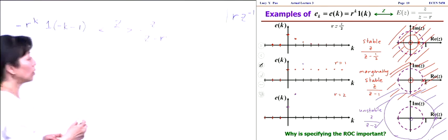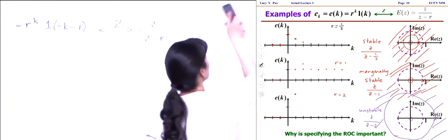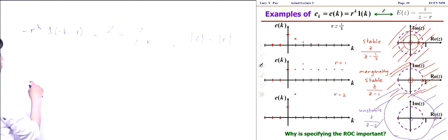Okay, where now the region of convergence is the opposite. So now its region of convergence is magnitude of Z less than the magnitude of R. Okay, and so this is acausal. It's a left-handed sequence, right? So if I call this, say, E of K,